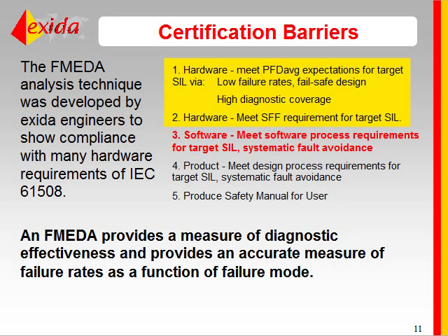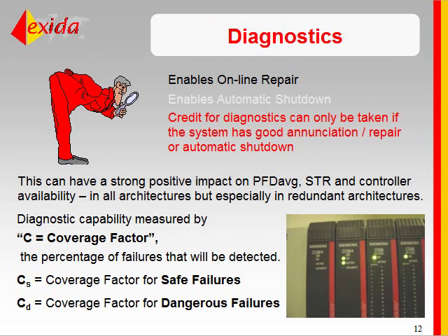One of the main reasons for FMEDAs, as we talked about, was to show compliance with IEC 61508. In fact, the FMEDA analysis technique was developed by FMEDA engineers to show compliance to many of the hardware random failure type requirements of 61508. An FMEDA is an analysis technique that provides a measure of diagnostic effectiveness and an accurate measure of failure rates as a function of failure mode.